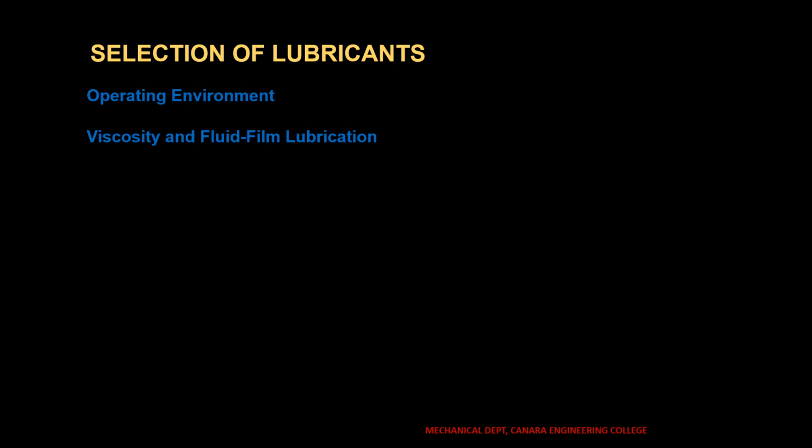Viscosity and fluid film lubrication. The low temperature operational capability of a liquid lubricant is defined by the maximum viscosity at which the lubricant can be pumped. The high temperature operating capability of a liquid lubricant may be defined by the minimum viscosity that can provide fluid film lubrication. The lubricant has to be effective in both the fluid film lubrication and the boundary lubrication regime.